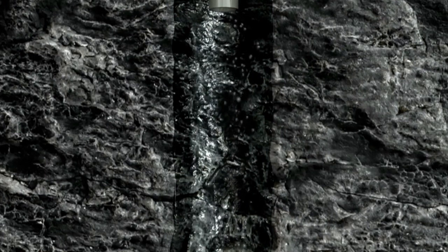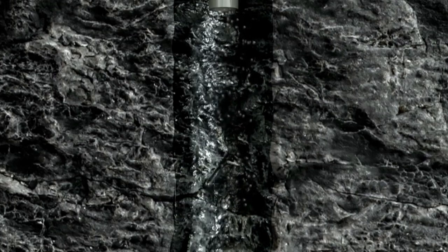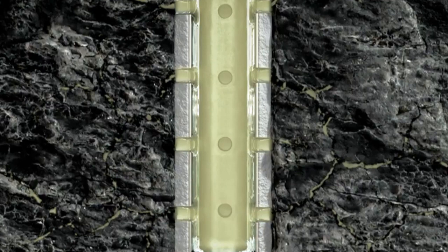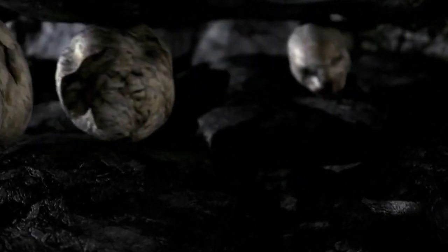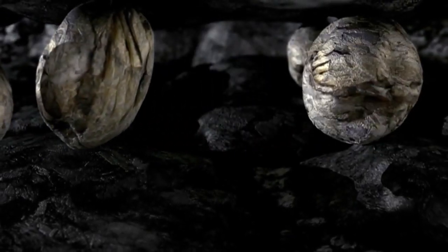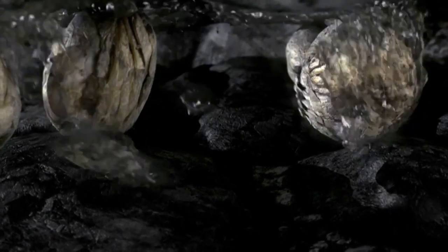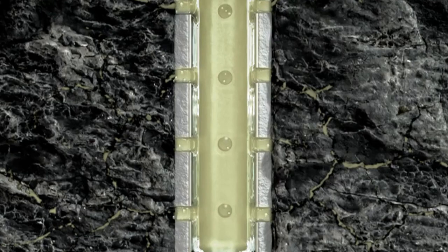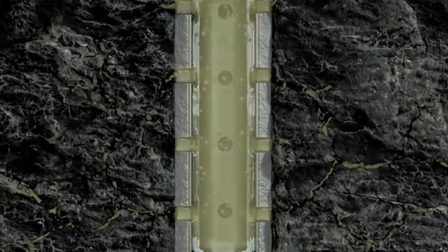Various techniques have been developed to enhance the amounts of gas that are released from the coal. One option is fracture stimulation, where fracturing fluid is pumped into the well at high pressure in order to enhance naturally occurring fractures within the coal, as well as producing more. The fluid transports sand into narrow fractures, propping them open and allowing the gas to flow into the well more easily. The fluid is 98.5% water and sand, with a small amount of additives such as guar gum, borax and citric acid, which are found in everyday household products.